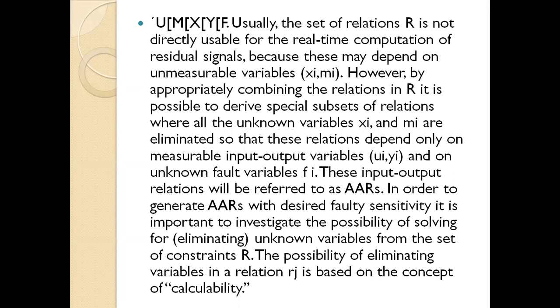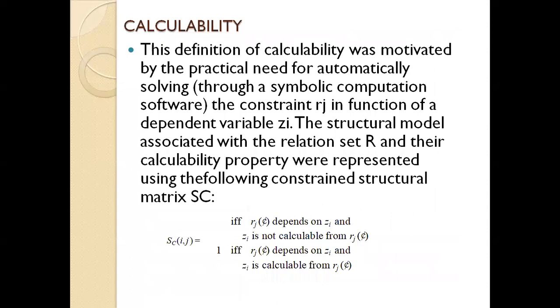In order to generate ARRs with the desired sensitivity, it is important to investigate the possibility of solving for an unknown variable from the set of constraints, which is the concept of calculability. Calculability. The definition of calculability was motivated by the practical need for mathematically solving the constraint Rj in function of dependent variables Zi. The structural model associated with the relation set R and their calculability property were represented using the following constraint structural matrix: Sc(i,j) equals 1 if Rj depends on Zi and Zi is not calculable from Rj.